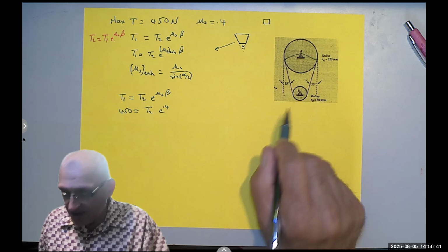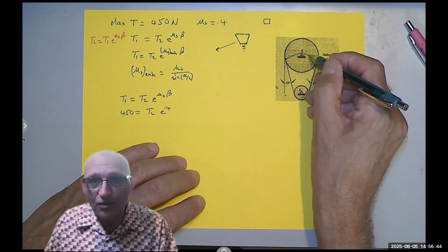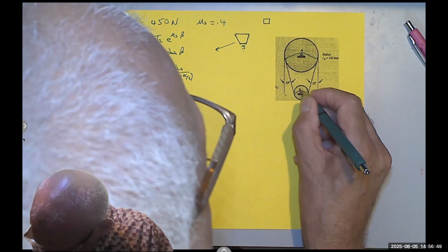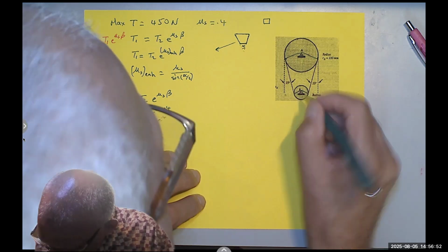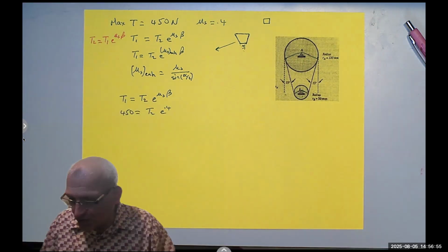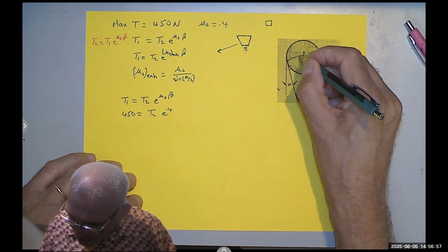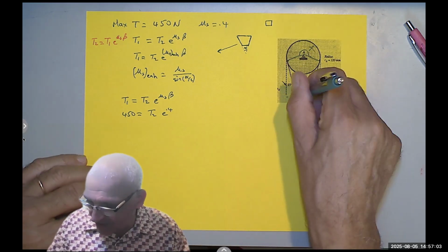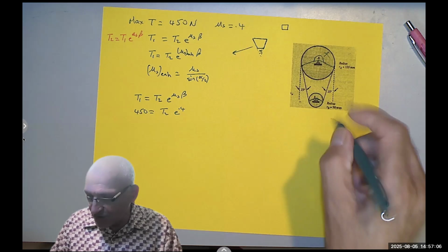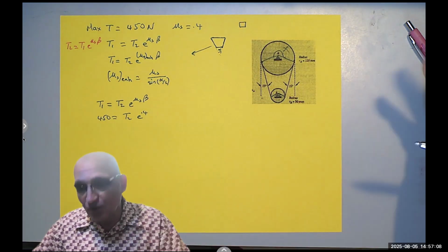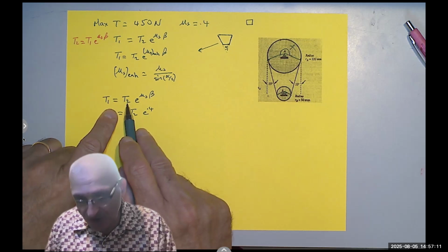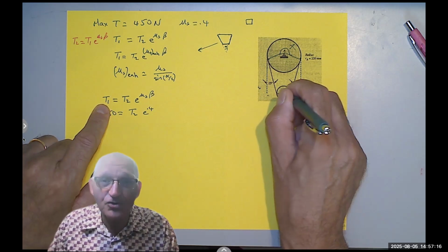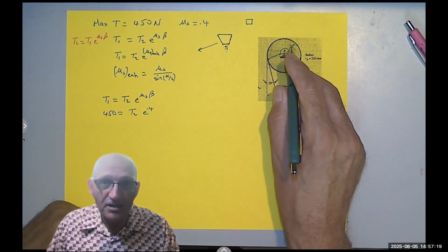You have to be careful here because we will use that at the end, but in the beginning, I'm turning the cable here. So that is beta that we are using, not that. In other words, the motor is connected to pulley B. That's what rotates, so that's what generates the torque, and that's what I'm going to use to find T2. So you have to look at the bottom or the smaller pulley, not the bigger pulley.